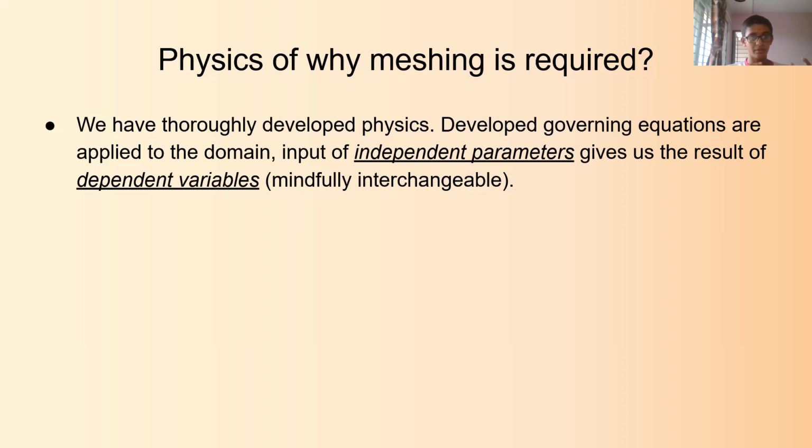First, you should be mindful of what kind of results you are looking for. You should not be just for fun looking for different kinds of results and plots. You should first think of what results you want to check, and then select that. Yes, I want to see the stress distribution, I want to see the strain, deformation, and if there are endurance properties involved, there is fatigue, then there are results related to fatigue, such as the stress after 10 cycles, the stress after 100 cycles, etc. Then if there is friction involved, there are contacts involved, then contact stress can come up. So there are different sets of dependent variables also there.